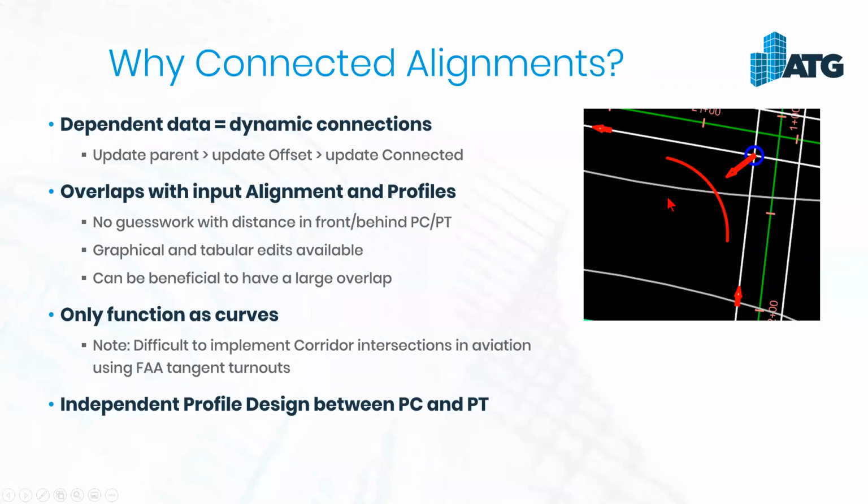So this is really great because it allows us to do two things, at least primarily, and there are more. This helps us make sure that we can have a good ADA access if we are designing some sort of a curb ramp through our sidewalk and this intersection. And it also lets us define whether or not our stormwater in this corner of our intersection is going to collect or reject water. So we can now have a profile view to do our stormwater design, and one more thing that we get to connect to the rest of our model.